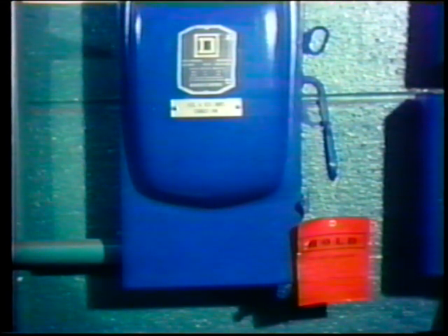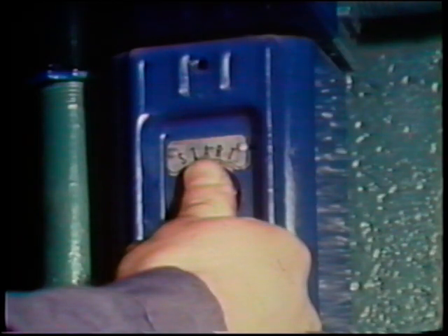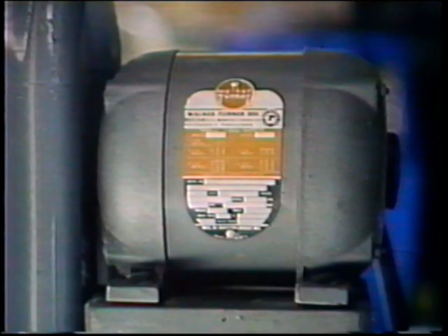But his task is not complete until he tests the controller for proper operation. To test the controller, the start button is pushed and the motor starts. When the start button is released, the motor continues to operate. The electrician allows the motor to run a few minutes more just to be sure. The controller problem has been solved.